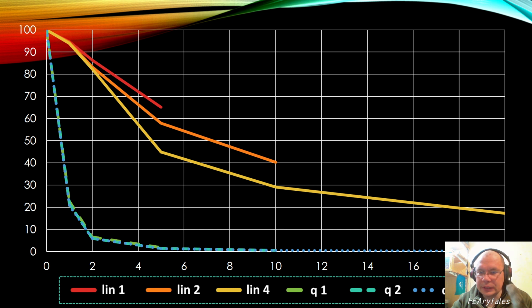But you need to understand that for CFD tasks, it's not the same. For thermal tasks, it works in another way. If we talk not about tetra elements but about hex elements, it's not the same. Yep, quadratic hex element is much better than linear hex element, but it's not the same type of behavior.